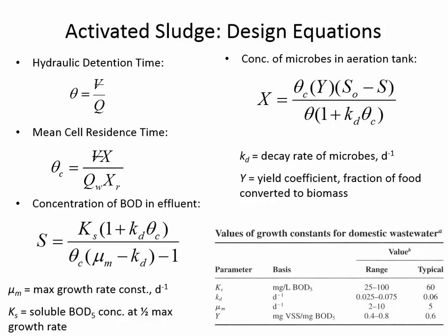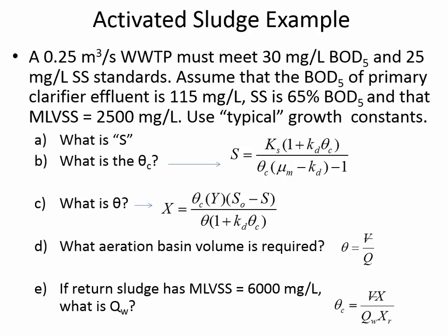You'll use some of that energy and burn it off. But the bacteria are much better at turning food into body mass. And the reason why we like that is the food they're eating, remember, is dissolved BOD. We have no way of getting dissolved BOD out of solution other than turning it into something solid that will settle. Okay, I'm going to illustrate this calculation on the board.